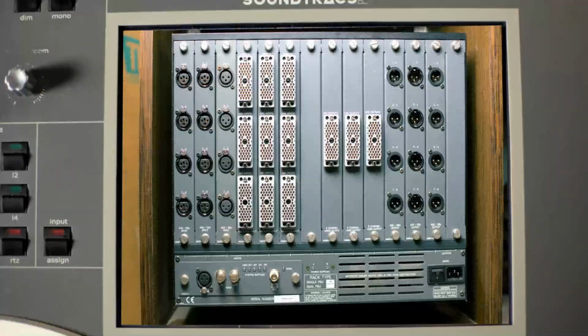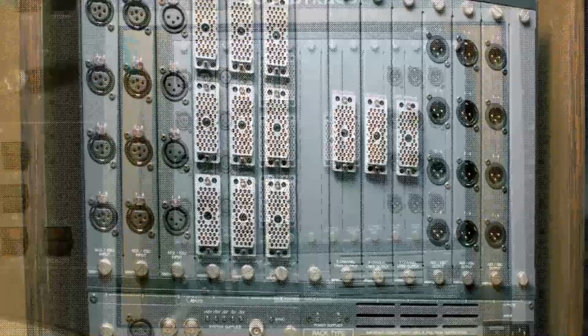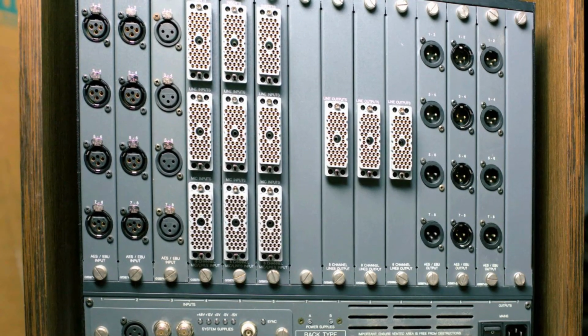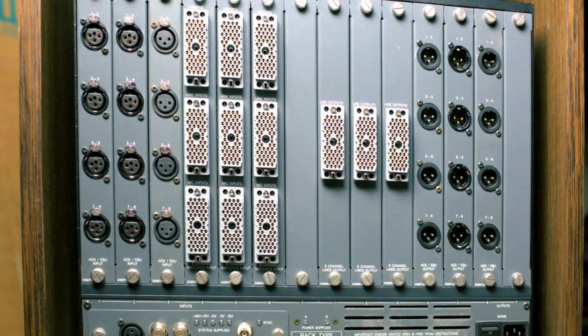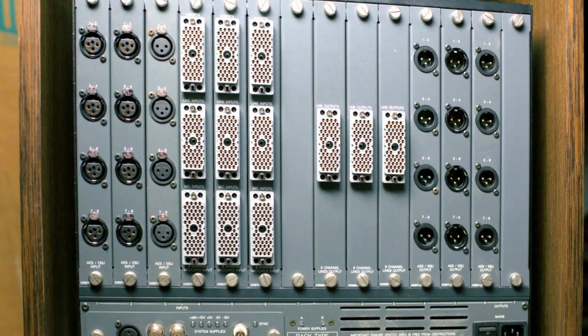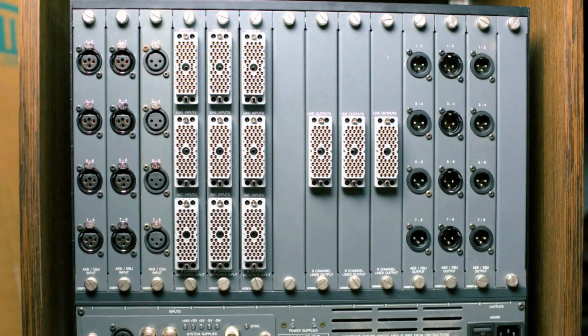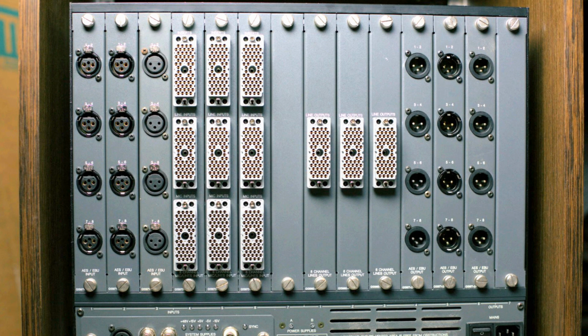The external MADI multi-channel audio-digital interface rack supplied with the console converts 24 analog and 24 AES EBU digital input signals. These 48 inputs are supplied to the console using a single coaxial cable, which can be up to 30 meters long. The 48 outputs from the console are sent back to the MADI rack by another coaxial cable, providing 24 analog and 24 AES EBU outputs. This digital to analog conversion achieves a staggering 114 dB signal to noise ratio.